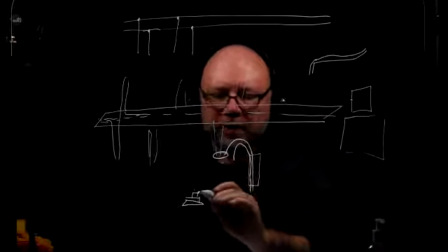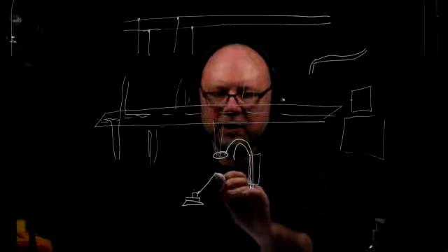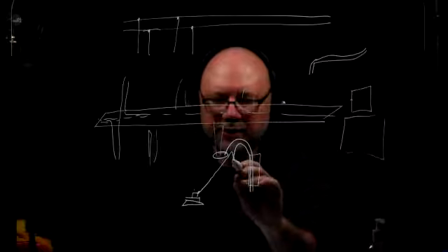One is going to go to common of the primary winding on the transformer, and the other one is going to go to the tap. We're going to show you. And then out of that, we're going to have a wire going into this spot right here. It's all going to be in the same spot, and that is going to be pigtailed as well.